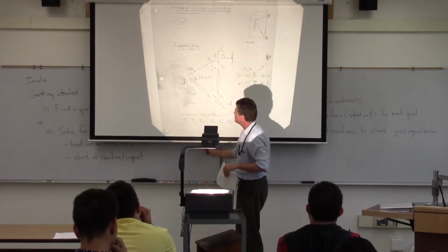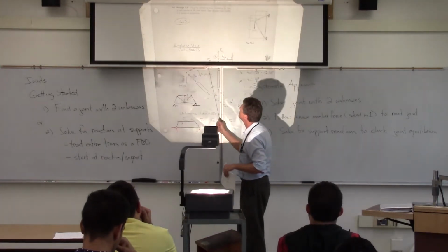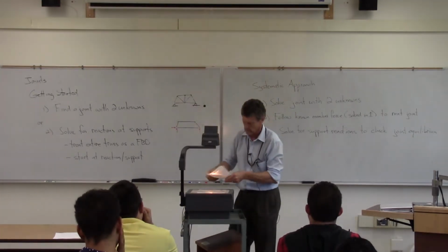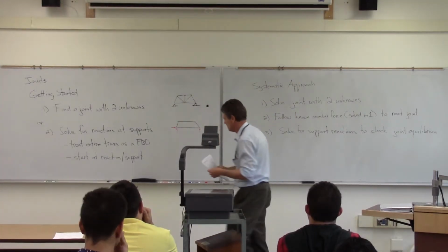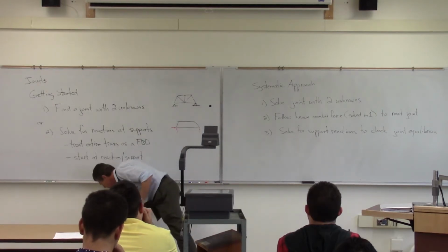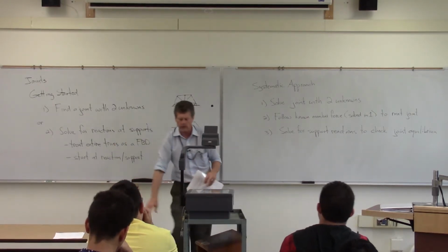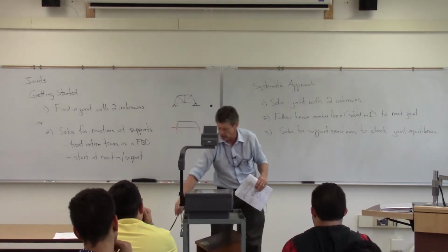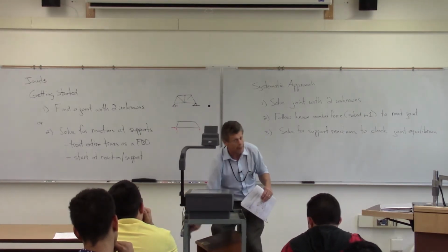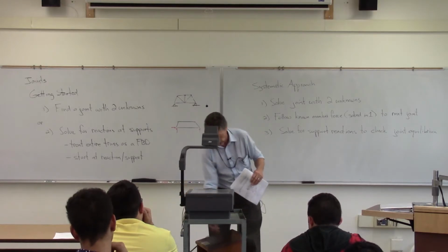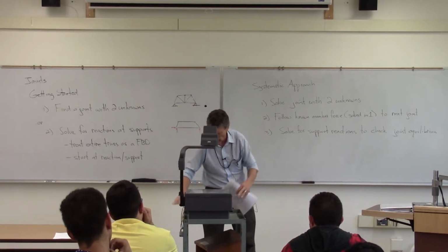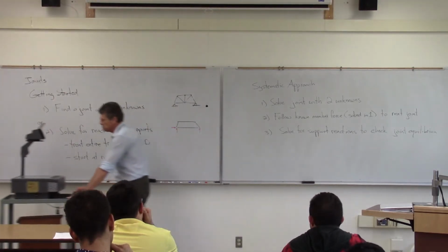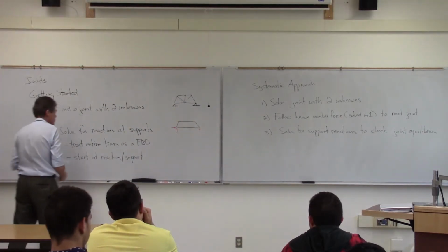Okay, so what we're going to do is go ahead and solve that problem via the method of joints. And what we're going to see is that, again, it's systematic, but it's the same thing that we've been doing. It's simply going to be draw the free body diagram, or you'll lose points, and then apply your equilibrium equations. Same thing that we've been doing in two-dimensional equilibrium.